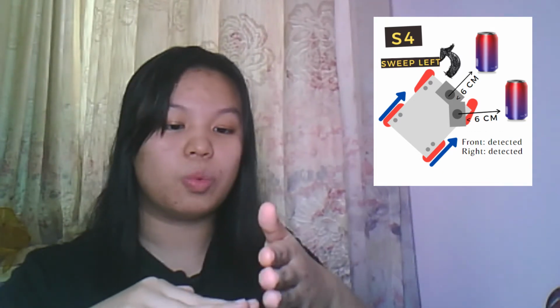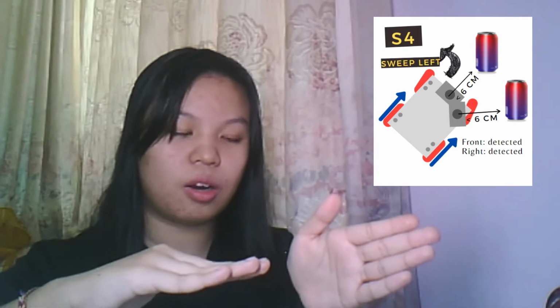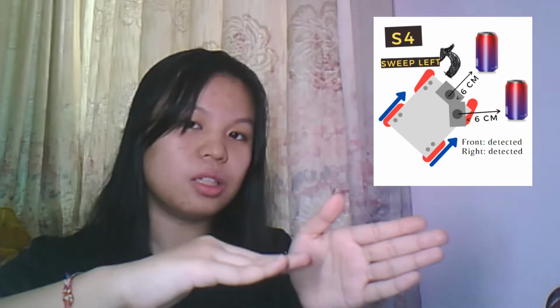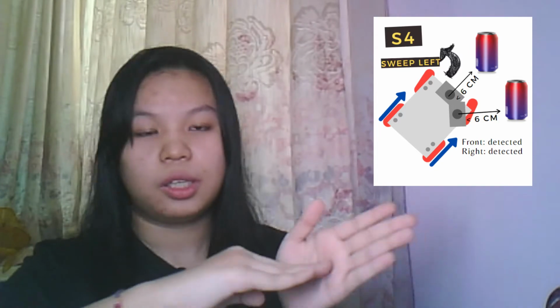Now we look at the fourth scenario, where the obstacle is not on the left. After checking, we see an obstacle on the right, but no obstacle on the left. Same thing, we push it towards the left, and again we ask the car to move just a little bit to help push the obstacle. When we combine scenarios 2 and 4, the front detector detects an obstacle, stops for a few seconds, checks left, checks right. In the fourth scenario, after checking, right has an obstacle and left has none, so the sweeper sweeps towards the left and our car drives towards the left a little bit to help push it. That is scenarios 2 and 4.